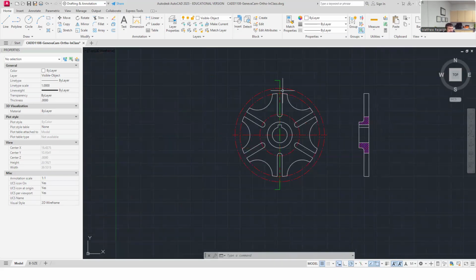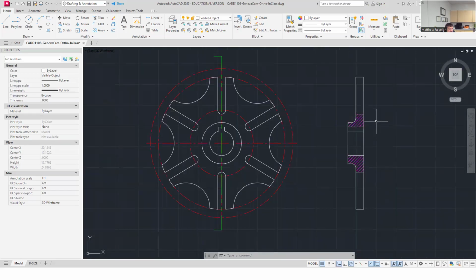So I have to remember when I took this section, I'm looking through some radiuses here, some radii. And so I'm going to add a center line across the middle here. And I'm going to add a horizontal center line for kind of the bottom of this radius too. And it could be argued that I would add this center line over here. It's not going to look very well centered if I add a center line for maybe this, so I'm probably not going to add the center lines that have to do with these at odd angles. I'm going to get one of them because it's on the same plane. Center line is the main hub bore here. But I don't think I'm going to add center lines to these. I'm just going to add them to these two where I've sectioned.